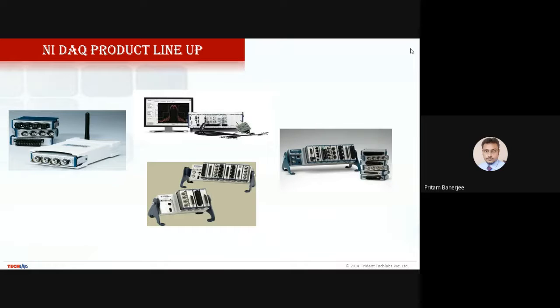And to generate or to acquire any of the signals from the real world, we need a data acquisition card. A data acquisition card is nothing but a combination of analog to digital converter and digital to analog converter. If we have analog real signals in the environment, to acquire that signal into our computer, LabVIEW will be the acquisition software, but hardware is also needed, like a data acquisition card, which converts that analog signal into the digital format. The digital format is acquired by the computer.